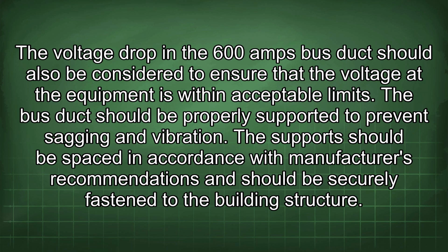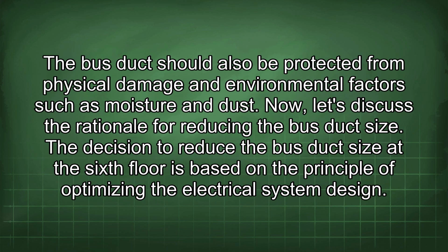The bus duct should be properly supported to prevent sagging and vibration. The support should be spaced in accordance with manufacturer's recommendations and should be securely fastened to the building structure. The bus duct should also be protected from physical damage and environmental factors such as moisture and dust.